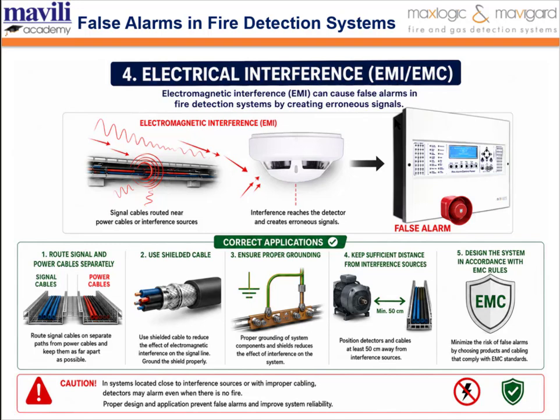The use of improperly shielded cables or improperly filtered equipment, routing signal cables along the same path as power cables, or inadequate grounding practices can cause this interference to be perceived as a false signal.